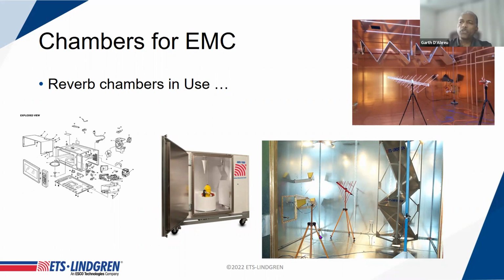Across the industry, they've been used under different standards. This example on the left covers handsets, cell phones, to a CTIA and 3GPP communications-related standard. These larger chambers, this one would certainly satisfy the ISO 11452-11 reverb test method for component immunity. And larger chambers would meet the MIL standard, DO-160, as well as the ISO 11451-5 new standard for vehicle testing. Again, just an example of the types of facility that can be used for performing these measurements.